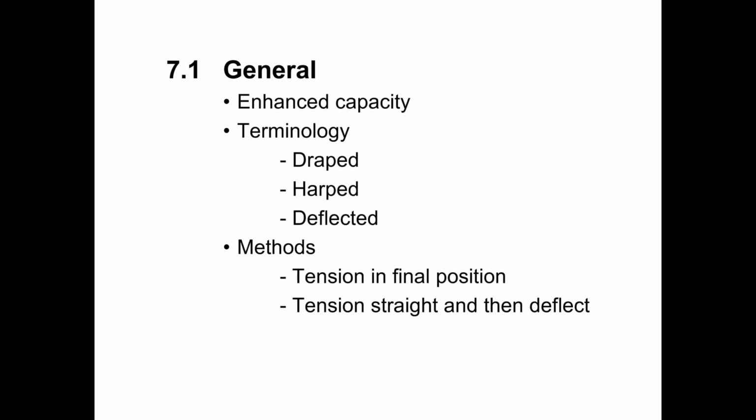All right, tensioning in the straight position and then deflecting the strands afterward, we kind of have opposite pluses and minuses. The plus of doing this is that we eliminate the friction at the hold up and hold down points that interferes with our tensioning tolerance. And so it's usually easy to get the strands tensioned within required tolerances if we tension them straight and then deflect them afterwards.